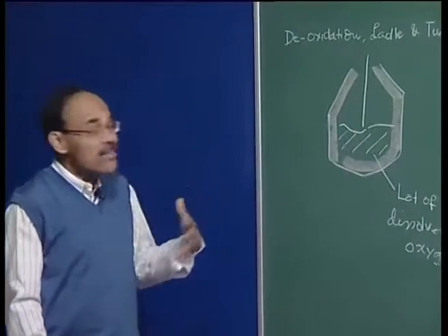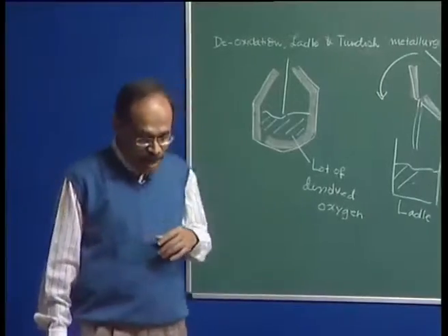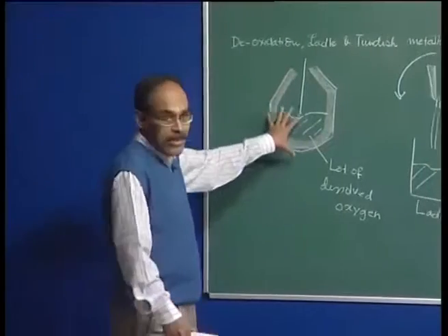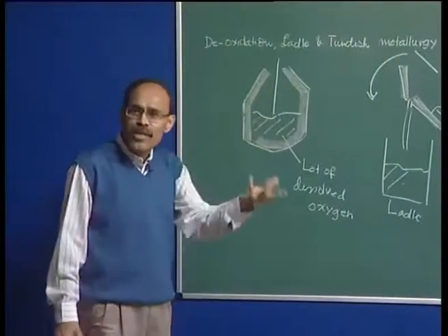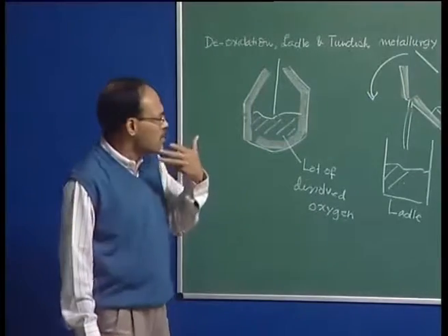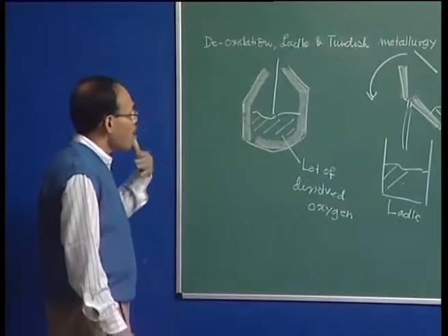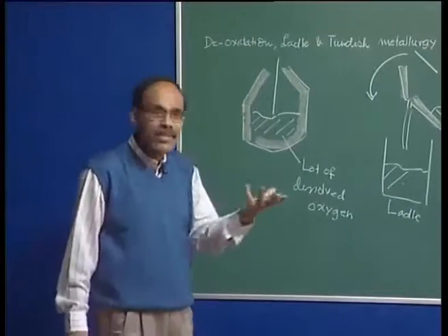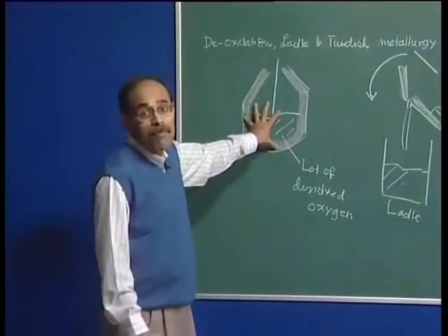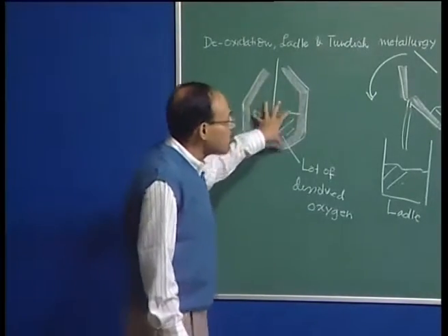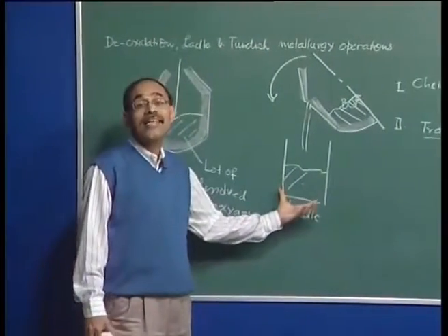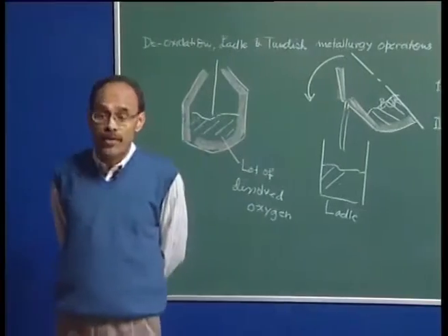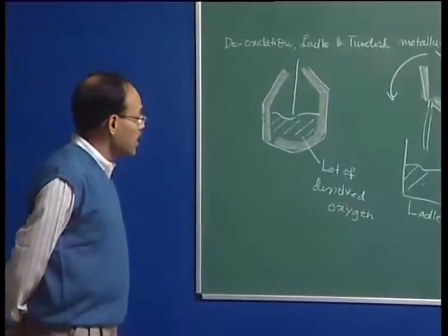So today the tendency in modern steel making companies is to use this vessel only for decarburization, and subsequent operations like desulfurization or composition adjustment or temperature adjustments can be carried out in a vessel beyond the primary steel making vessel, and there we will see as we advance that the ladle will evolve into a very useful reactor, which we will call the ladle furnace.